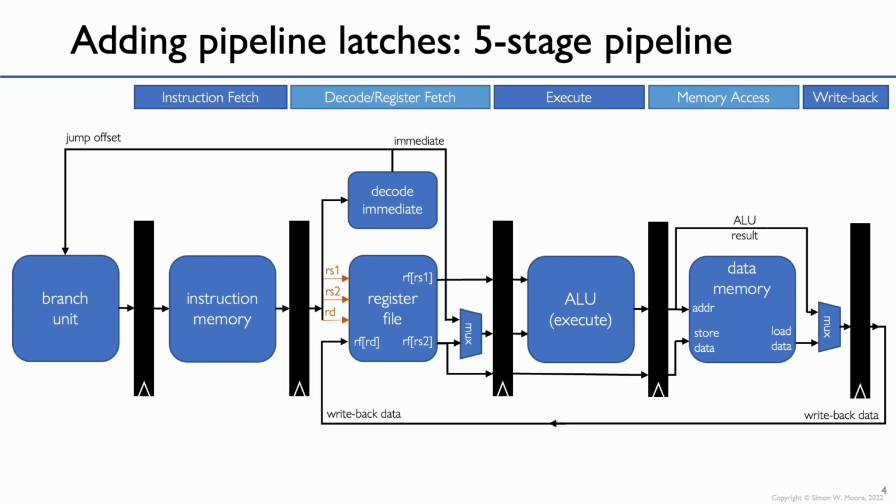So if we then use these banks of D flip-flops, we can use them to form a 5-stage pipeline. And note here that we've got 5 banks of D flip-flops in sequence, and therefore this is a 5-stage pipeline. It's perhaps easiest to think of the D flip-flop being at the beginning of each stage in the pipeline.